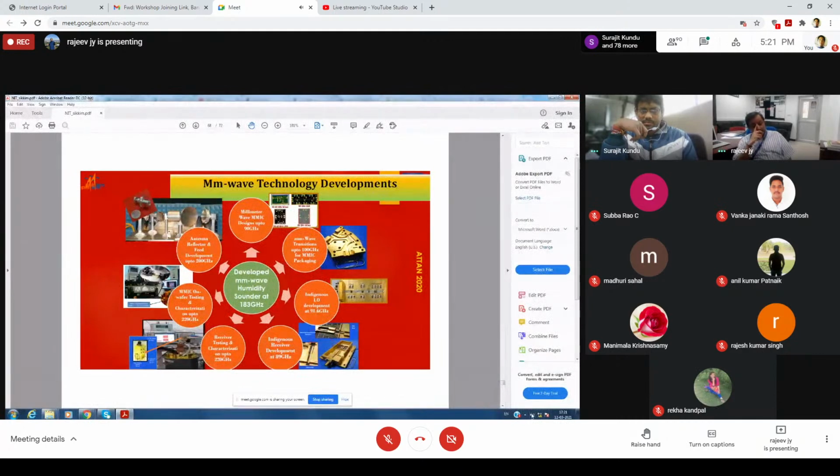And the third way is spatial separation. Normally for any satellite we keep in orbit, we keep nearly 1 degree separation, which amounts to a large distance; I am talking about 1 degree in subtended angle. That itself helps, because if the ground station antennas have a wide beam, then they are seeing all the satellites. Normally that happens for a small size.